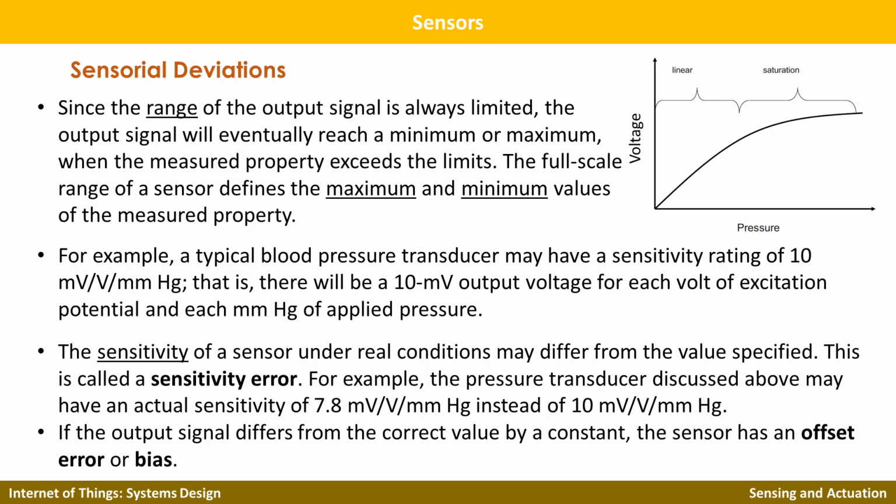But if this offset value is changing over time, which is part of the calibration, then it becomes troubling to recalibrate and add this gap between 7.8 and 10. You can do some manual calculations, but then again you need to think about how critical these measurements are when you are correcting issues such as offset errors and bias.